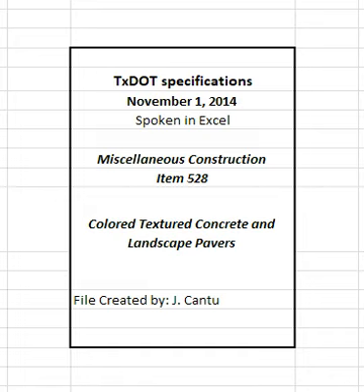Loosen pre-compacted sand or screeded sand in advance of the laying phase only to an extent to which paving will be completed that day. Lightly screed the sand in a loose condition to the predetermined depth slightly ahead of laying the paving units. 3.2.4 Paver installation.